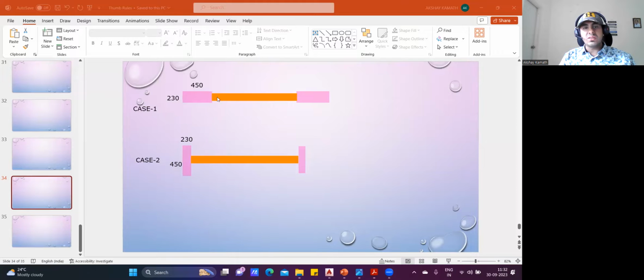Okay, now you understand. See, here you are trying to bend. So this 450 depth is there, and this also 450 will try to stop this bending. That is the depth of the column parallel to this direction. Whereas here, when the load comes on the beam and it tries to bend, only 230 and this side 230 is there, whereas the majority 450 is going down. So in this orientation, only 230 depth is there to take care of that. That is the reason for what we usually do.